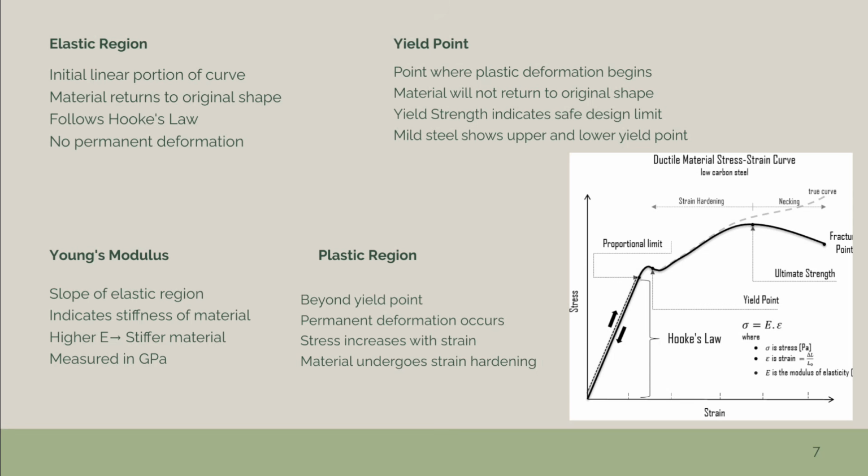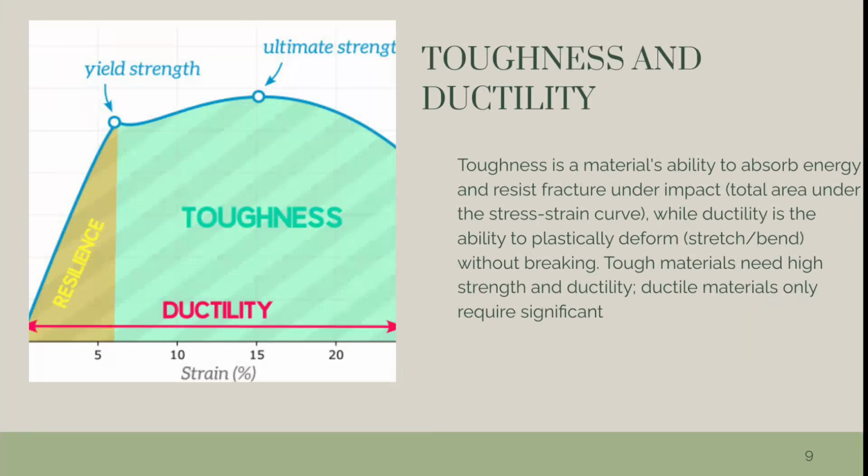The third stage is the necking region. Beyond the tensile strength, a neck forms where the local cross-sectional area becomes significantly smaller than the average. The necking deformation is heterogeneous and will reinforce itself as stress concentrates more at the reduced section. Such positive feedback lets necking develop quickly and leads to fracture. Note that although the pulling force is decreasing, the work hardening is still progressing.